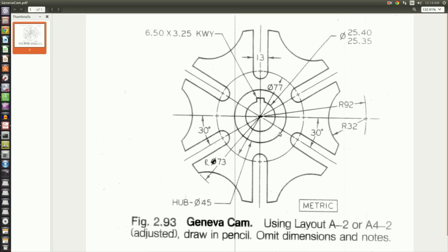For this drawing, there's lots of ways we can go about it. You notice it's very symmetrical. We could mirror side to side, we could mirror up to down, we could draw a quarter of it, mirror it over, and then mirror it down again. Lots of ways we could go about it, but instead we're going to do a circular pattern of it. So what I'll do is draw this part here and this slot, and then we'll pattern the whole thing, and then we'll be done.